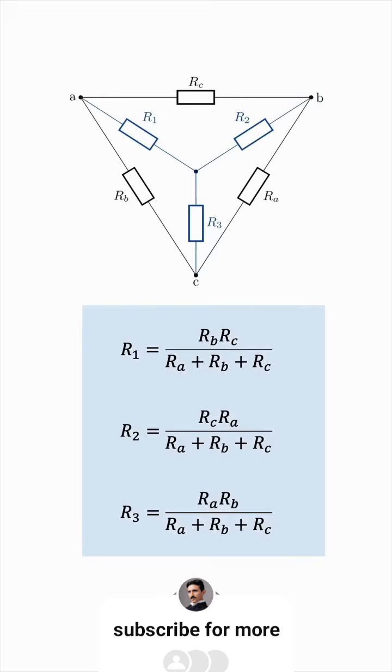Notice that the denominators are all the same, but the two resistors in the numerator are the resistors adjacent to that resistor. So for example, for R1, the two resistors in the numerator are RB and RC, the two resistors next to it. Using the delta to Y transformation, we can find the equivalent resistance of complicated networks.